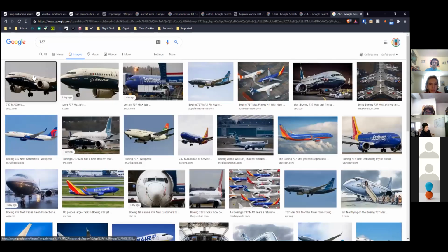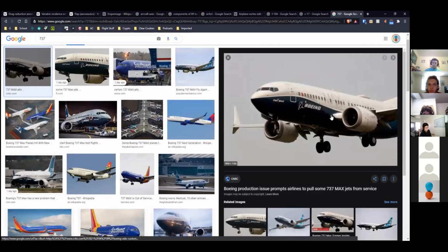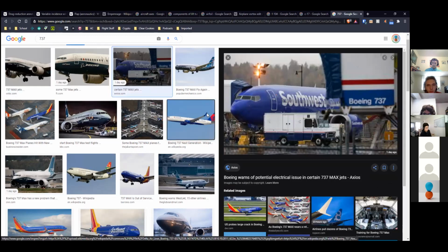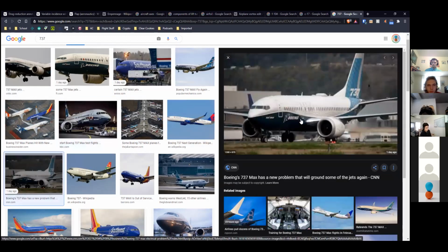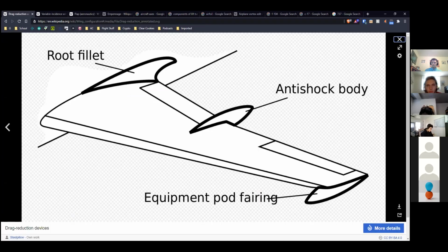So see this thing, the landing gear lights, this whole wing box that goes through here basically has a root fillet built into it. If I could only find a picture, yeah. So see how the wing doesn't just smash into the end of the fuselage and have a sharp line there. The whole thing's kind of smooth together because that will help your interference drag. Okay.